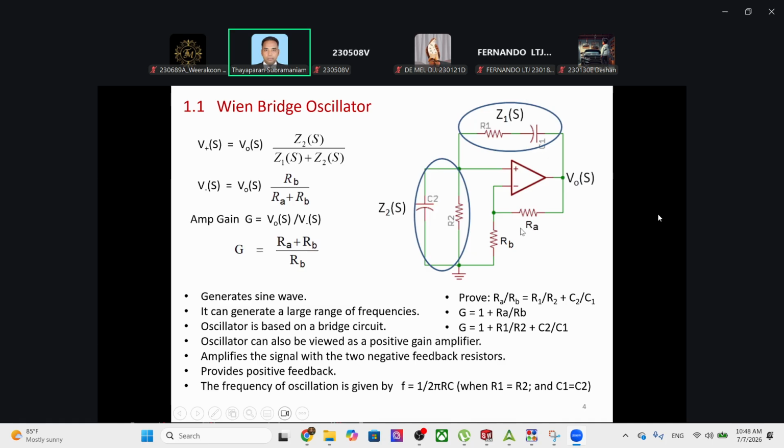The other one is designing the amplifier. Look at the characteristic equation. Ratios matter here, not the actual values. So RA, RB in megaohm or kiloohm, R1 not needing to be in megaohm or kiloohm, it doesn't matter, as long as the ratio is maintained and we have this governing equation relationship, that is fine. C1, C2 in nanofarad or microfarad doesn't matter. Why? If it is microfarad, that will be cancelled out. Nanofarad, that will be cancelled out. Eventually, the C2 over C1 ratio matters.